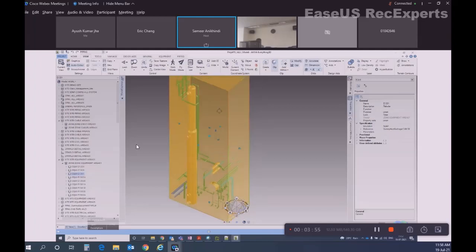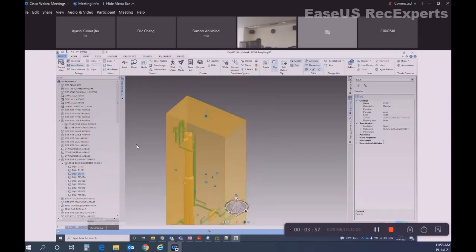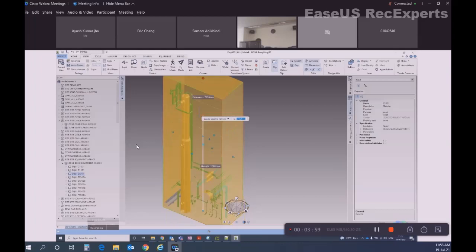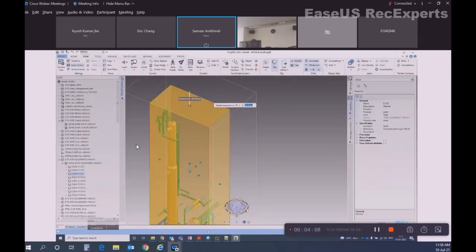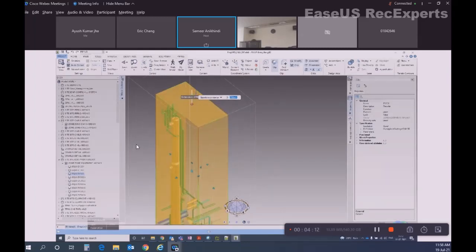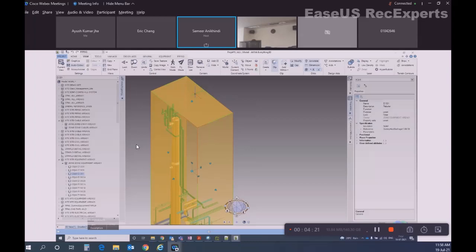Or what you can do is go to the drop down before entering a value. You can use expand the box. So what it is doing, it is calculating the value from the current point, you can expand the box fully by 500 mm. So it increases 500 mm in all directions.